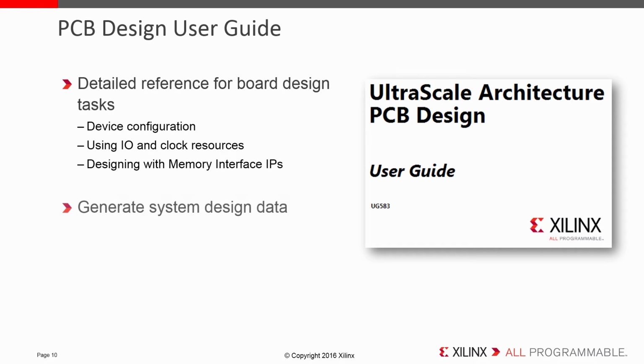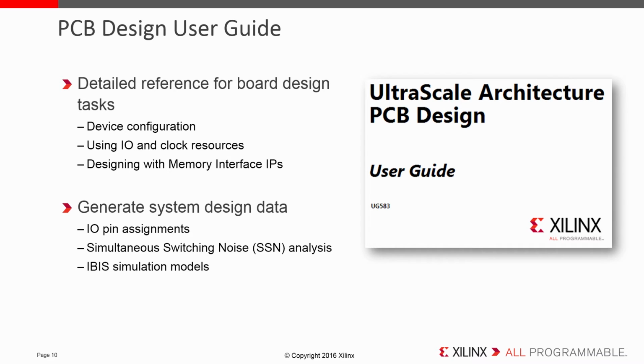And the PCB Design User Guide also covers how to generate critical data for the system designers, such as the actual device I/O pin assignments, simultaneous switching noise or SSN analysis results, and IBIS simulation models for signal integrity analysis.